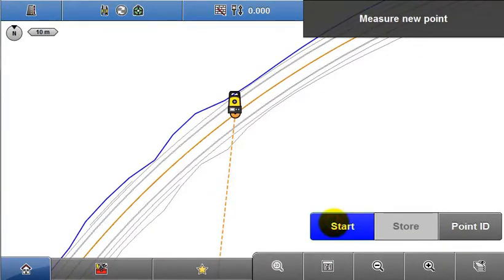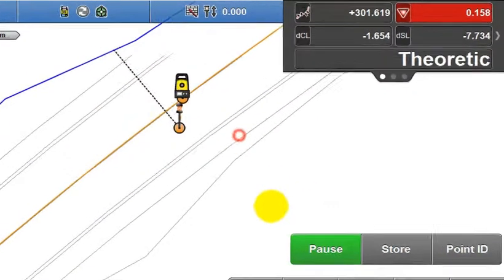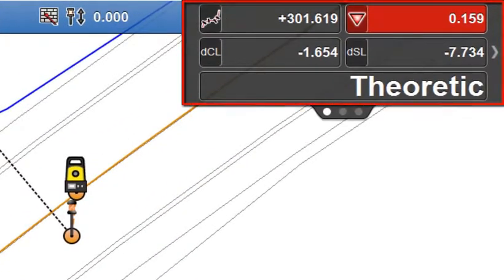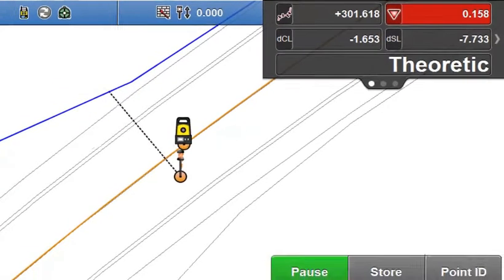Once measurements are activated, positional data relative to the selected string line at the current chainage is displayed in the info panel. For example, chainage and cut and fill are displayed here on the top line. This info panel can be configured as per each application for iCON site.